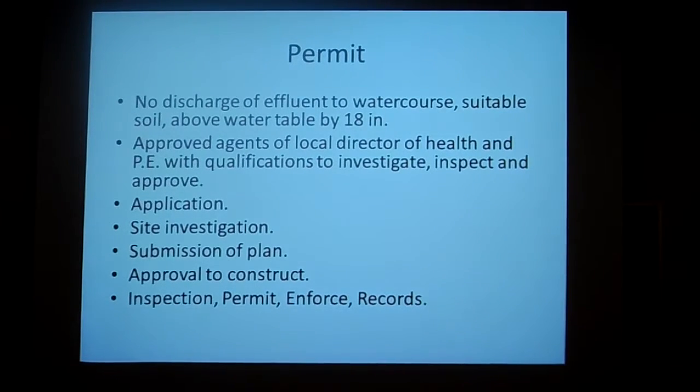Some of them being that you are not allowed to discharge effluent to a water course, you need to have suitable soil, and they need to be above the water table by 18 inches. In addition, they need to be approved by agents of the local director of health and or a professional engineer with qualifications to investigate, inspect, and approve these septic systems.